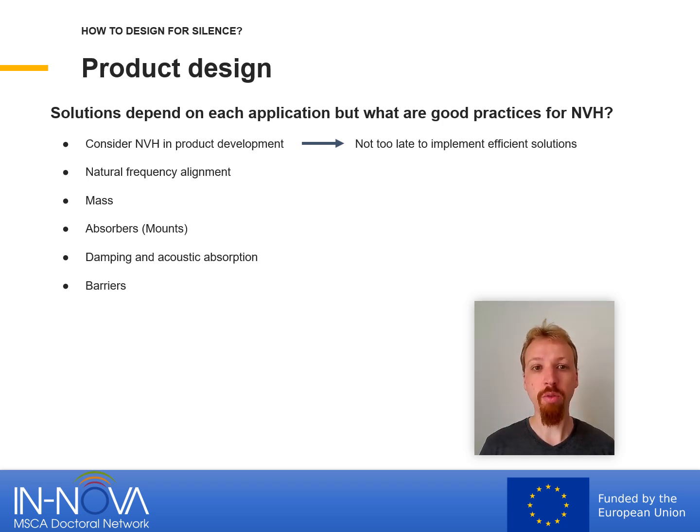Take care with the natural frequency alignment. The natural frequency is a frequency where your component will have a peak response with a little excitation. Avoid it so you avoid resonances. Take care between the natural frequencies of the many components that make your product so they don't match or tune their natural frequencies.